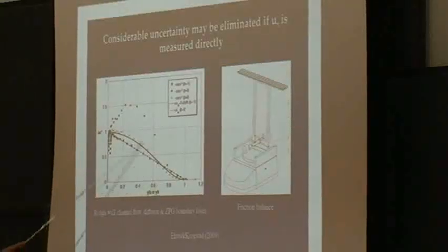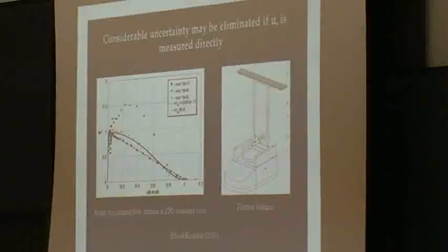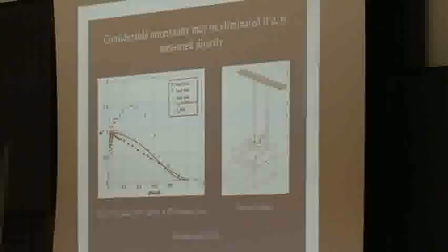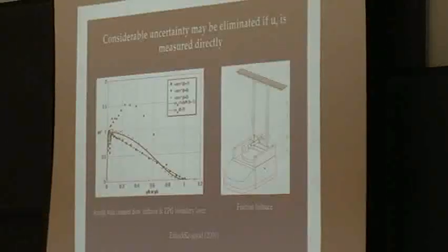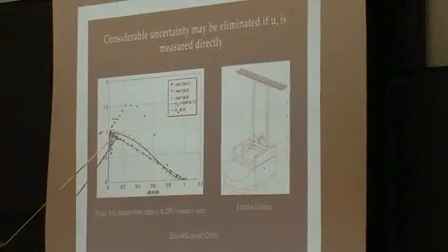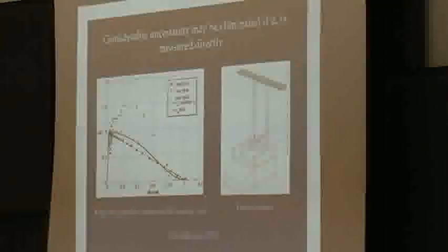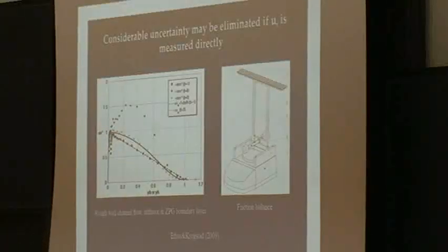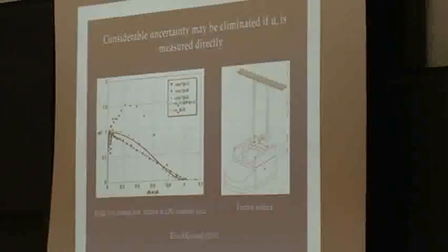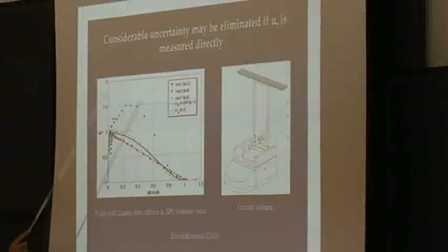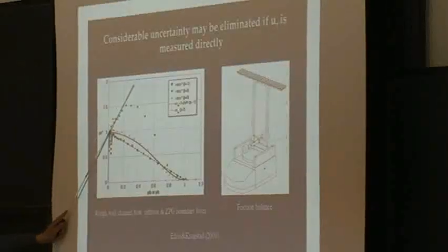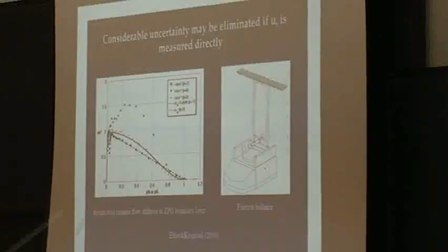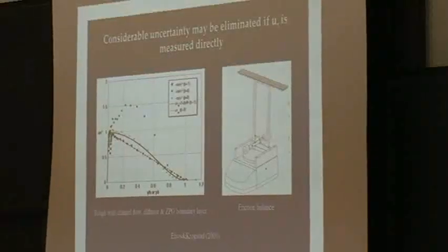And then we did the same type of measurements for a zero pressure gradient boundary layer. And again, you see that we have very good collapse with a theoretical curve. This one was obtained by integrating the momentum equation, and then the measurements that we have. And finally, we used the balance on a diffuser, which had a non-dimensional pressure coefficient of 6, and we got this nice linear shear stress distribution, which extrapolates back to the wall.